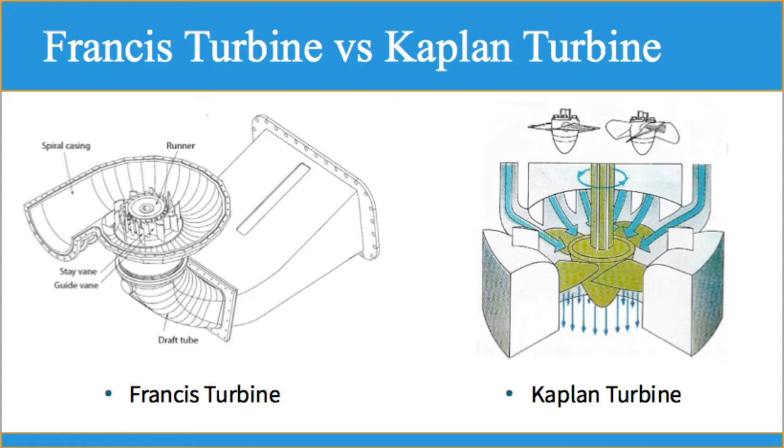It's not clear, but these turbines are kind of shovel shaped, and that water can be fed down as they're being spun. And on the right is the Kaplan turbine, a much simpler design. Water is being fed from top to bottom, never changes direction, spinning this propeller. Now, as you can see on top, this would be the most sought after design, where the turbine blades can be rotated, changing the speed of the shaft to generate electricity.